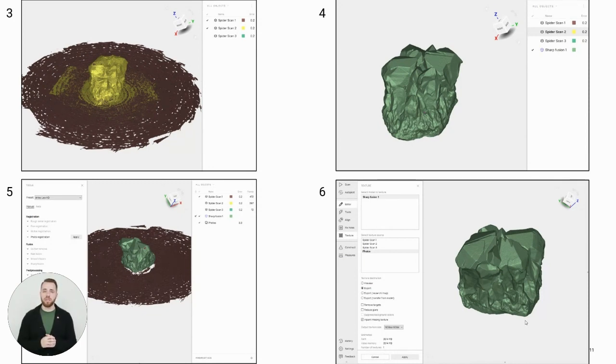During texturing, we should exclude both scans from the texture source and only use the imported pictures. Okay, so that is basically the technique. We capture the object's texture first. We do not spray it. Then we take pictures of it. Then we apply spray. We scan it for geometry. We use that geometry scan for fusion, right? We get fusion from it.